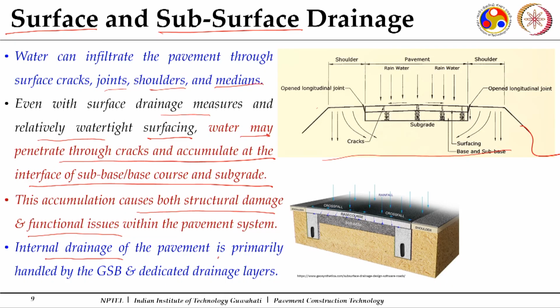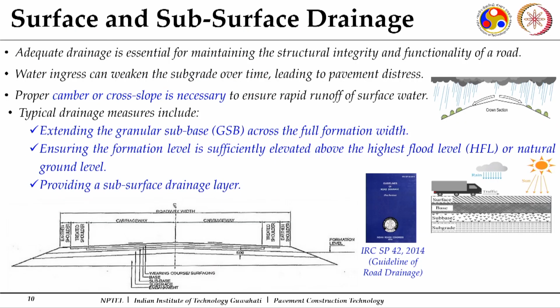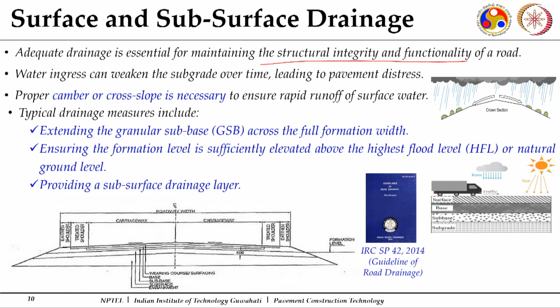Internal drainage of the pavement is primarily handled by the granular sub-base course, or you provide some dedicated drainage layers. We will see how that is done. Now, the main measures taken for surface and subsurface drainage serve, as I said, the structural integrity and functionality, and my purpose is to prevent water from getting ingressed into the subgrade or my granular courses during the service life.